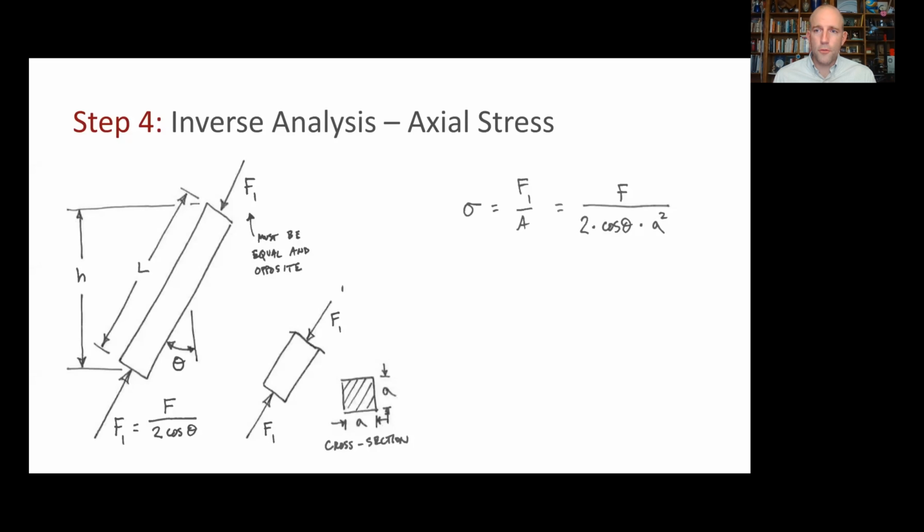All right, so the first step is pretty straightforward. We're going to substitute the yield strength over the factor of safety for the stress. That's what we want the stress to equal. And if it does, then we'll get our factor of safety exactly.